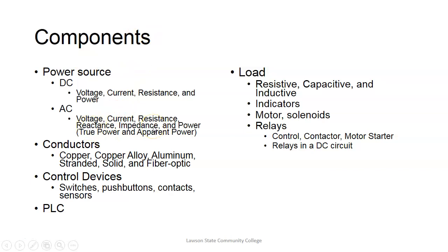We don't have to worry about impedance, which we run into in AC. And of course, the information we're sending is constantly changing. Plus, we don't have to worry about electromagnetic interference that we get from any conductor or anything carrying AC. So there's a lot of advantages of fiber that gives it the ability to operate at extremely high speeds.